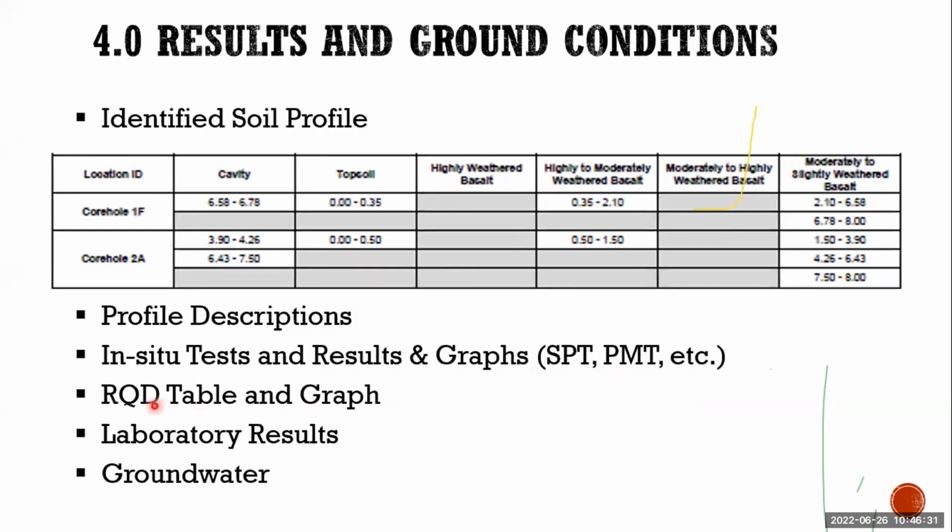And if you encountered rock, you can include the RQD with respect to the depth in an RQD table. RQD is rock quality designation, which will be helpful if you do tunnel projects or any pile foundations. Then you can include the lab results and the groundwater.